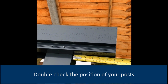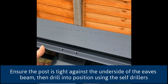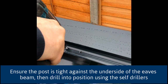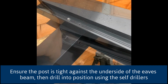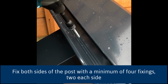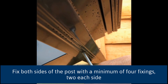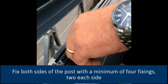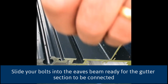Now just double-check the position of your posts. Ensure that the post is tight up against the underside of the eaves beam. Then drill into position using the self-drillers. Fix both sides of the post using a minimum of 4 fixings, 2 each side, unless it's a downpipe post where you only need to fix the post from the back. Then slide your bolts into the eaves beam, ready for the gutter section to be connected.